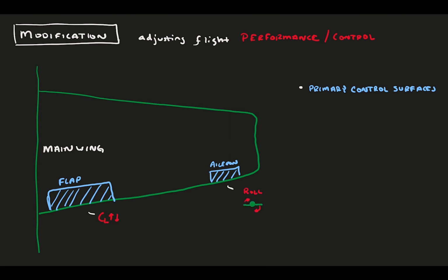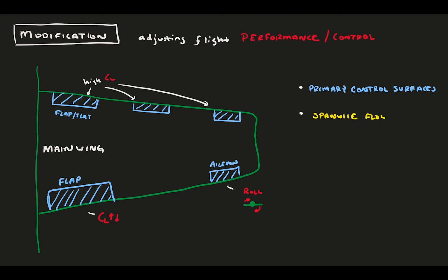In the leading edge, we can have flaps or slats in various places for when we need to go to very high angles of attack, as we saw with modern airfoil design. Secondary to these are the flow control devices over the surface. Some are designed to control any flow that moves in the spanwise direction, or sideways in this view. It generally is unwanted and hurts performance. Fences, notches, and teeth are all used to mitigate spanwise flow.